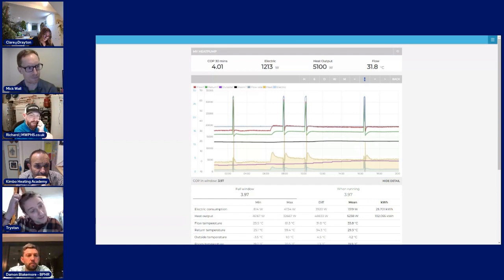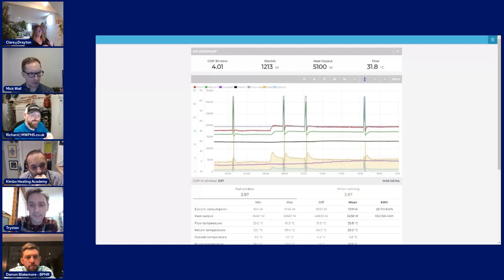Yeah. Another example is we've been monitoring a Daikin system where the data sheet says it should achieve 10.8 kilowatts at around 0, and over a number of defrost cycles, we couldn't get more than 7.6, so that's like a 30% below datasheet result. So you'll often see that Daikin systems are oversized to take into account this discrepancy.